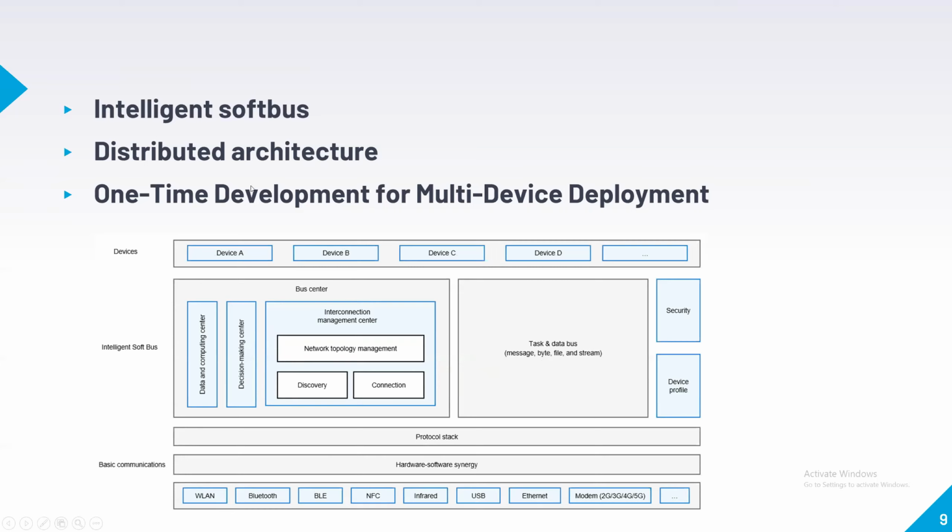Once that header is received by device A, it starts a connection over Bluetooth. Once the connection is established, the Bluetooth link exchanges the Wi-Fi information. Once the security information is exchanged, a Wi-Fi Direct link is established.